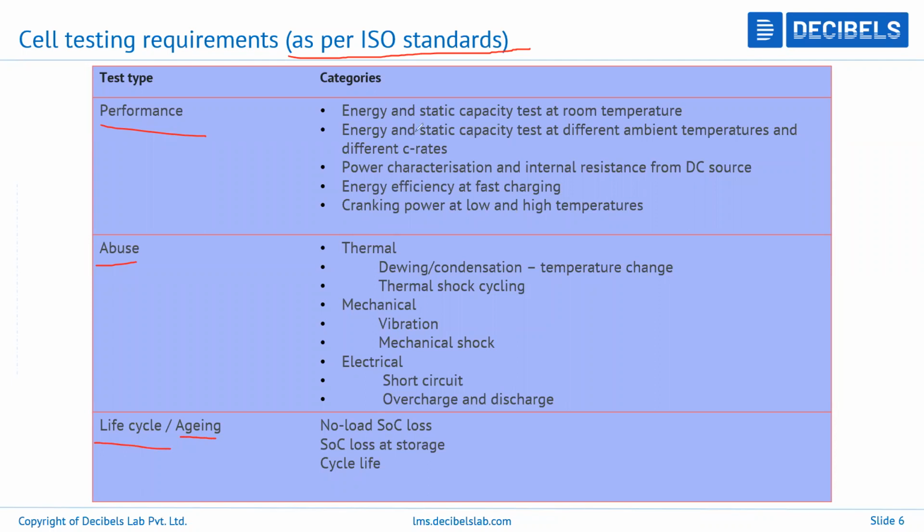In the performance test, you have all of these categories. Static capacity test and energy test at room temperature, and also at different temperatures, at different C rates or different current magnitudes, pulse power characterization, internal resistance tests, energy efficiency at fast charging and fast discharging. And finally, cranking power or low temperature cranking.